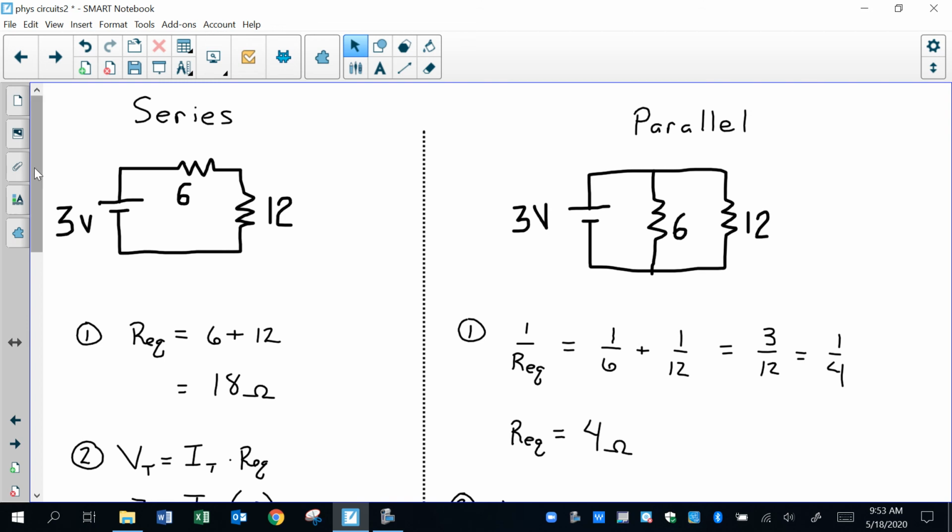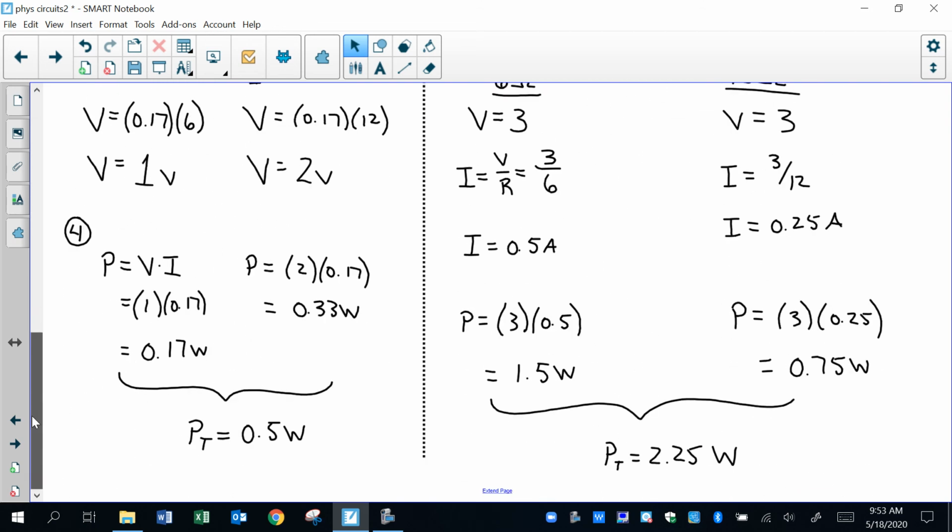So besides the convenience factor, the other reason here is if you connected everything in series, it's going to share the voltage. Instead of everything getting its own voltage, it shares the voltage, which means that everything's going to run way dimmer than if you would have just connected it in parallel.